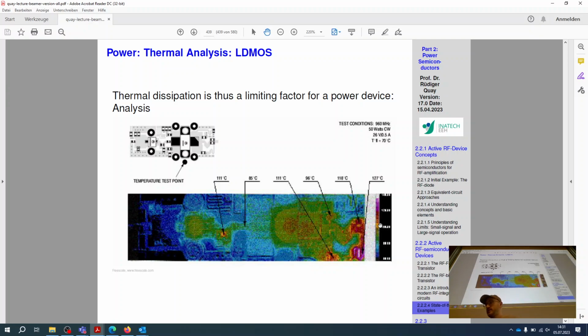Usually that is for an A/AB amplifier, class amplifier, then you move further to C class amplifiers and so forth. Your efficiency decreases depending on the input drive as well, so how much input power you drive into the device. That is why, when we apply a DC bias to enable the generation of the RF output, we have a lot of losses, and these losses are heat.